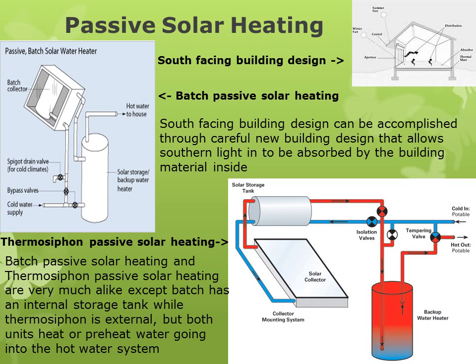During the winter, the sun gets low enough that it goes through the windows and gets absorbed into the absorbent material that the building is built with on the inside, either concrete or some other heat absorbing material, that absorbs the heat from the sun during the day and gives off this heat back into the building during the night.